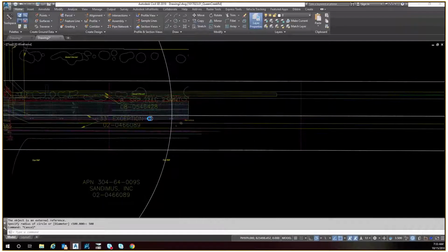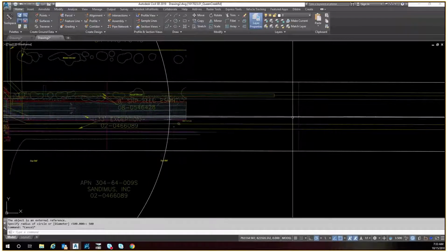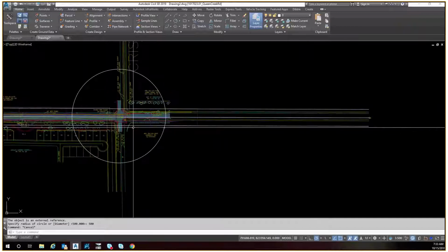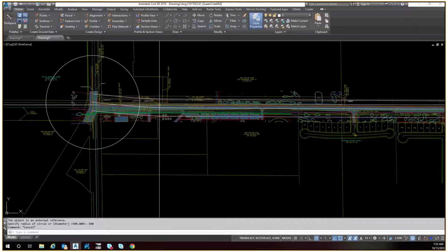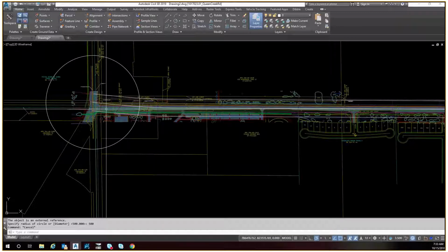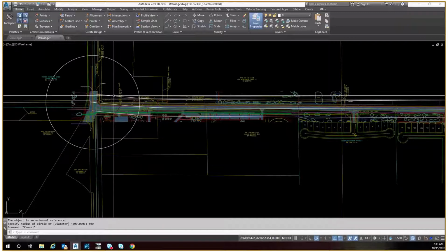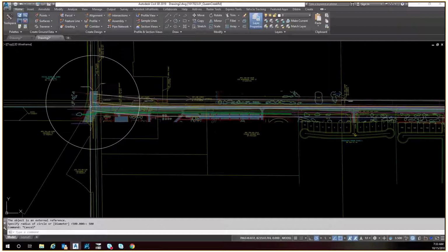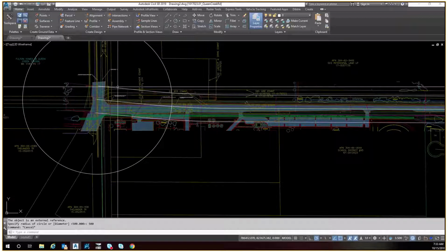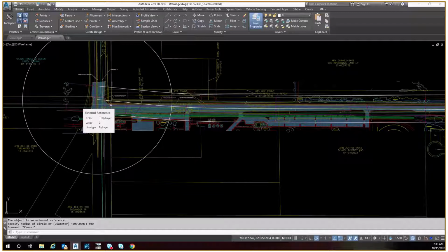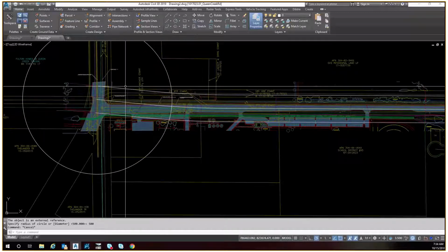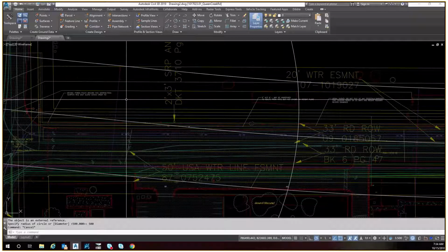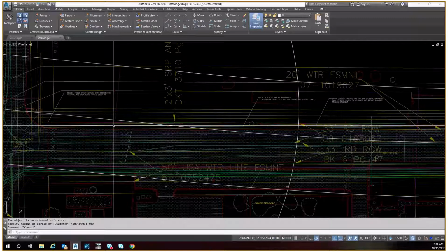And over here, job ending here, I'm going to need to go at least a few hundred feet beyond that in order to include everything and make sure that any striping tie-ins or any tie-ins that I need or any information I need that's adjacent is included. So I offset my center line 90 feet on each side to give a general width for my layouts. Now I need to determine where I want my sheet cuts to be, the vertical lines on the edges of the sheet.